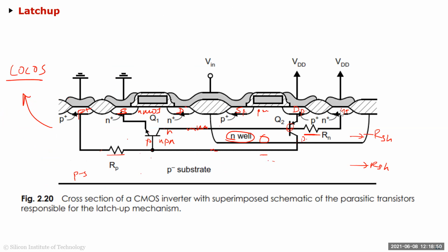If you see, on the P substrate, we have always been showing that we make a contact here, but this is a planar process. Every contact has to be made from the top. You cannot make contacts here, right? That's the bottom. In some processes you have backside contacts, but all your transistor connections have to come from the top. So when you make it from the top, let's say this contact was made somewhere here.